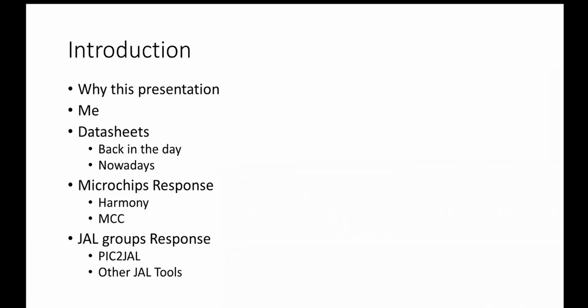One of them, which we'll not be touching today, but I'm quite happy to talk about it some other time, is called Harmony. And Harmony is for what I call big ticket items. Things like a USB bootloader or a CAN bus bootloader, a TCP/IP stack, that sort of big item.